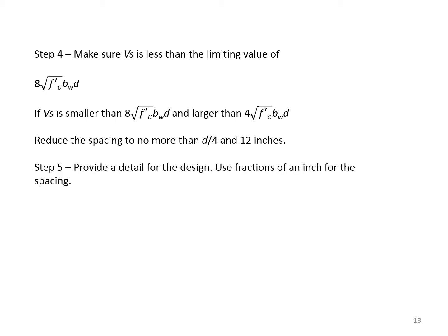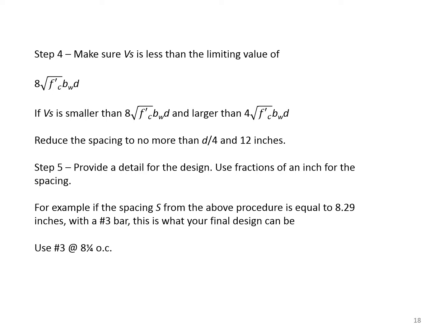Step 5. Now provide the detail for the design. Use fractions of an inch for the spacing. For example, if the spacing S from the above procedure is equal to 8.29 inches with a number 3 bar, this is what your final design could be. Use number 3 at 8 and a quarter inches on centers.